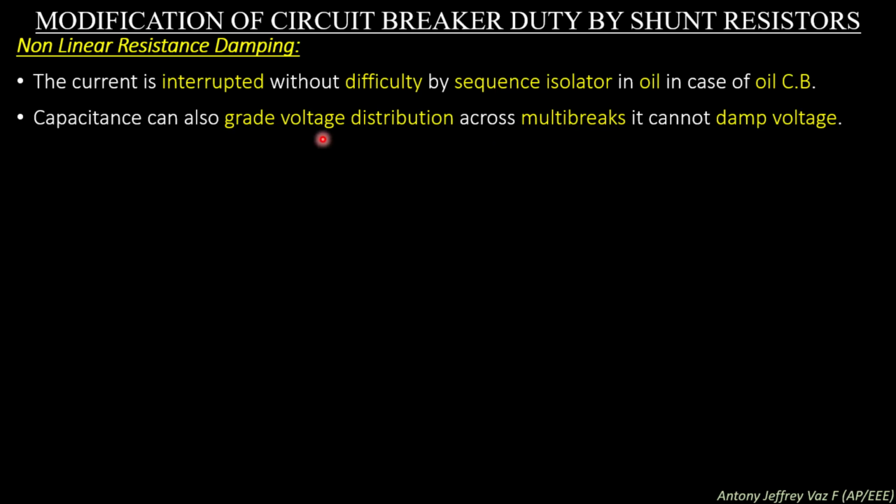Capacitance can also grade voltage distribution across multi-breaks. But nonlinear resistance damping, while grading voltage distribution across the multi-breaks, cannot damp voltage when capacitances are used. So this is a disadvantage of nonlinear resistance damping compared to capacitance damping.